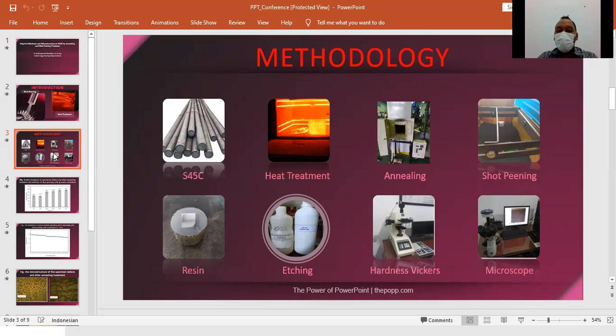After that, the specimen was taken from the heating furnace. The peening treatment process is carried out for 20 minutes. This parameter is the optimum distance that has been tested. The type of peening granule is S230 steel balls with a steel ball diameter of 0.85 millimeter. The peening treatment is carried out with pressure variations of 4, 5, 6, and 7 bar.